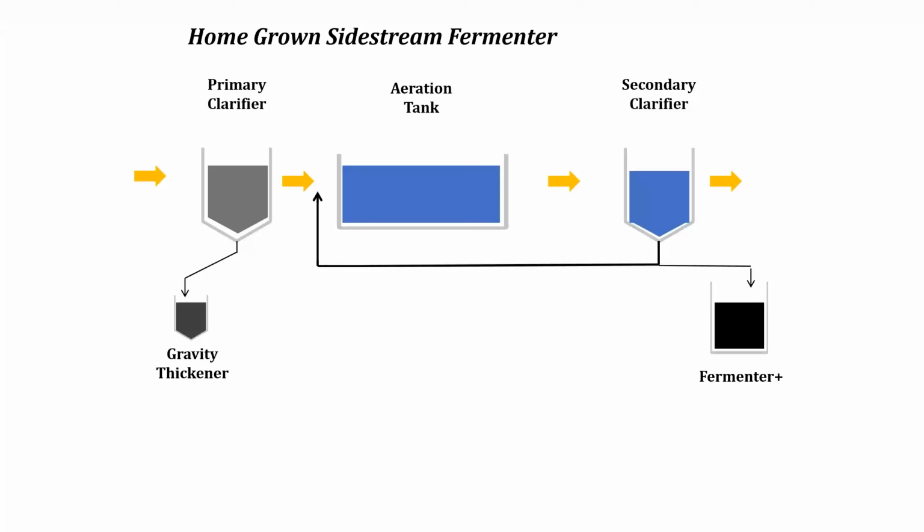So we want to manage that a little bit, so that instead of guessing, we run the air off enough consecutive minutes every day so that the bottom foot or so of that aerobic digester drops to an ORP of minus 200. It goes septic enough to create the volatile fatty acids.